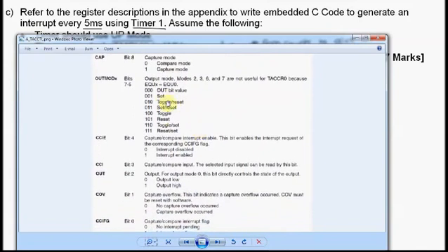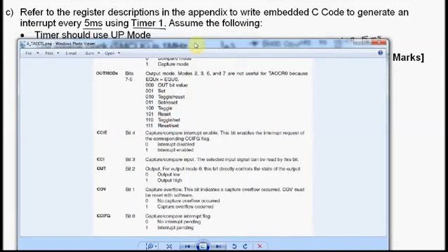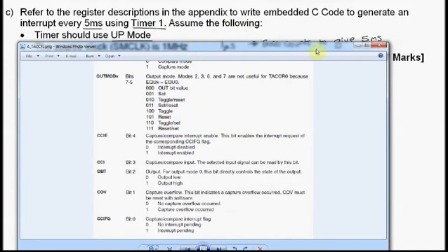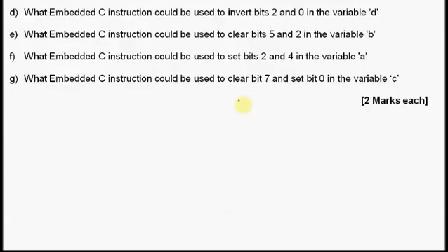It might be on toggle or something like that, and we use that to toggle a specific pin connected to a capture compare register, like TA0CCR0 or TA0CCR1. One final thing on this, we'll need to make sure our interrupts are turned on globally, so we use the function eint, and that will turn on interrupts for our device.